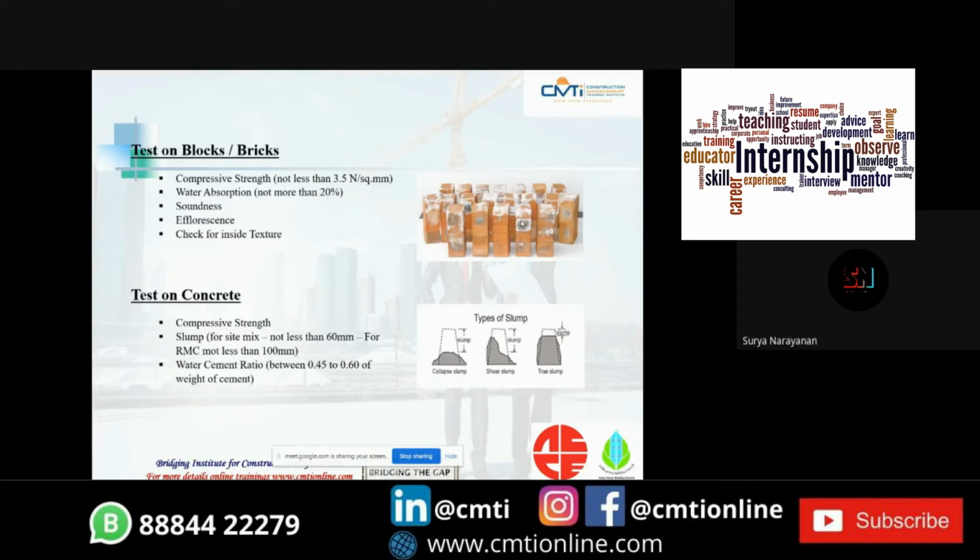So next is tests on concrete. Testing on concrete is done by compressive strength, slump test, and water cement ratio. For the slump test, site mix should not be less than 60 mm, and for RMC it should not be less than 100 mm. There are three types of slumps, as you can see in this image: collapse slump, shear slump, and true slump. Collapse slump is found when the water cement ratio is high, and true slump is commonly seen, which can be used for construction. It's good for construction too.